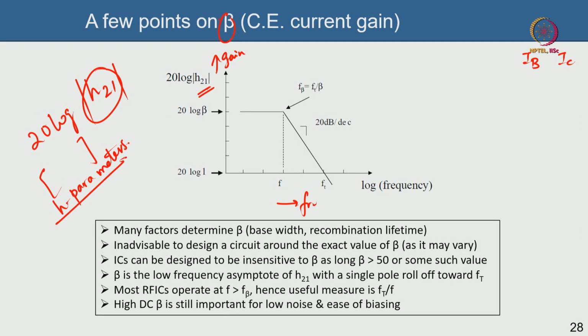H parameters are like 2-port network parameters. There are many parameters: Z parameters, S parameters, Y parameters, H parameters, ABCD parameters. You can think of these as matrices which are used to describe, characterize and understand microwave circuits, 2-port networks specifically, when you have an input port and an output port, and the way the waves go in, reflect and get transmitted can be understood with the help of these different matrices. They have different uses. For instance, experimentally you are going to measure S parameters, but the gain is given by the H parameter, it is easier to visualize that way.